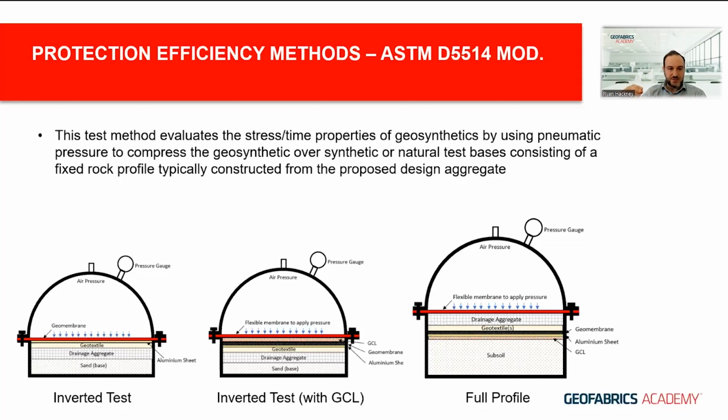And we use a fixed rock profile, and that's made from the site-specific aggregates. These diagrams just give you a few of the different types of tests we do in this apparatus. This has sort of evolved over time. Traditionally, this methodology was an inverted test where we have the drainage aggregate on the base, the protection geotextile, followed